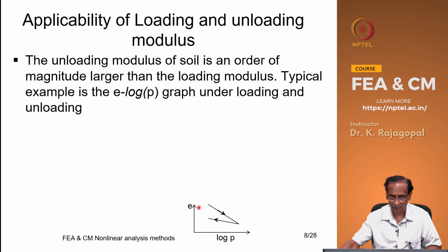So if you plot your E log P graph, this could be your loading part, and during unloading we will not go along this line, but only some small part of the void ratio is recovered. So we might get a response something like this, and this is our unloading response, and this is our loading response.